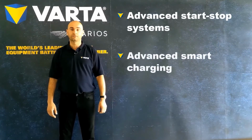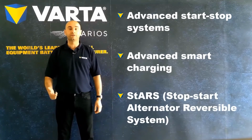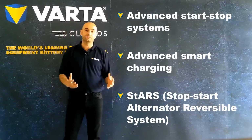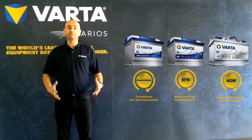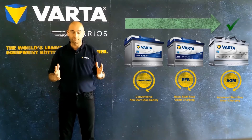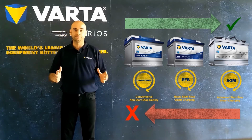smart charging, STARS, which means stop-start alternator reversible systems, as well as engine recuperation, plus cars with premium equipment and sophisticated accessories. As you can see, there are various battery technologies, be sure to replace like for like. You can always upgrade, but please, please never downgrade the battery technology.